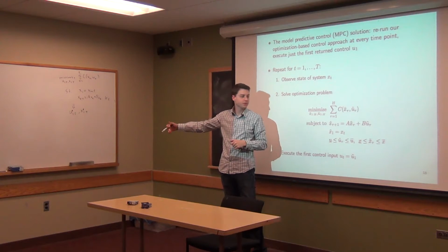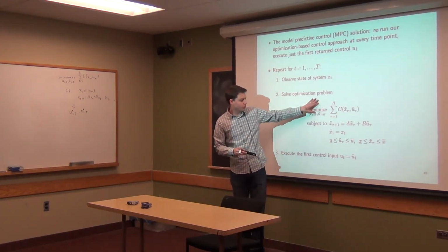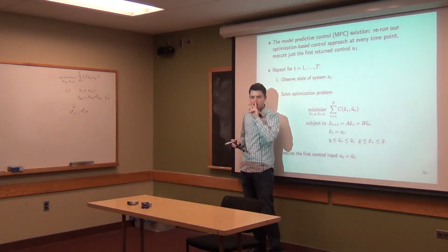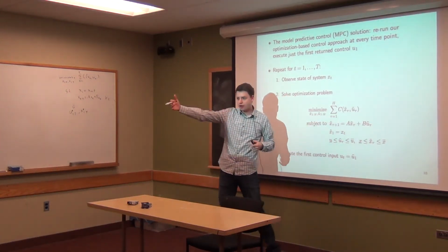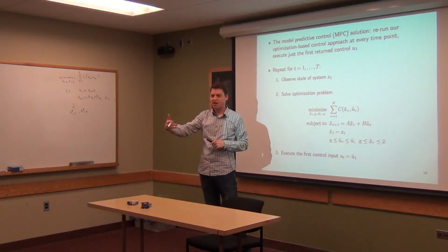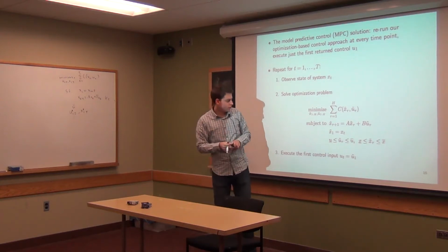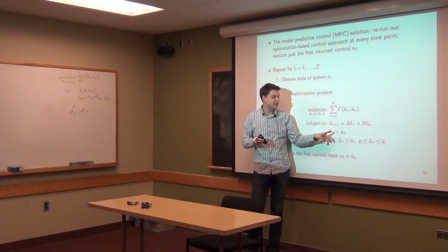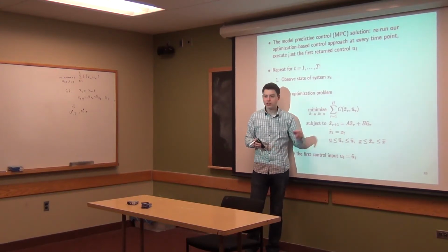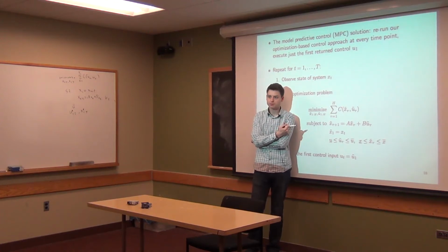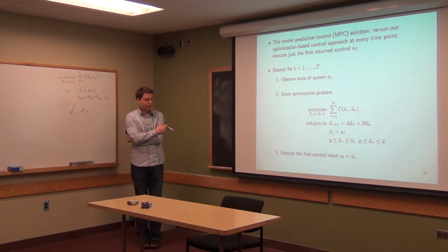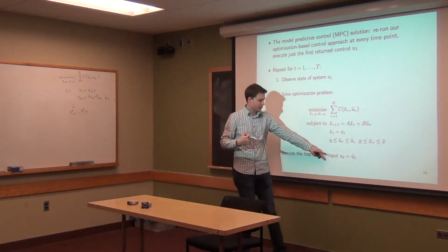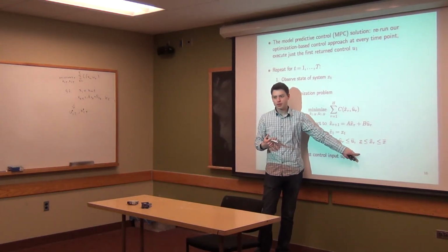We're going to plan the rest of our actions, right? So what we do is we solve this problem here with these x tilde and u tilde variables. And it's important to understand that we are solving this problem for a long time in the future, under our expectation of what's going to happen, with the first state of this initialization equal to the current state. So x_t is always the x init of our optimization problem here. Then we get some set of optimal controls out of that, and we pick the control that was just the first one we prescribed there. We repeat the whole process.